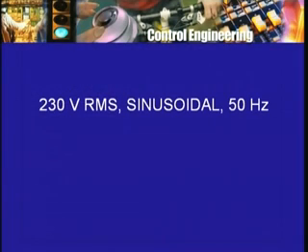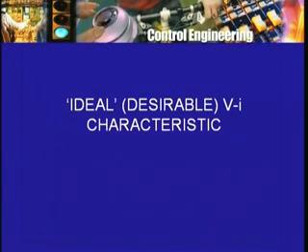In the case of the AC power supply, let's say 230 volts, it should remain in RMS value, the waveform should remain sinusoidal, and the frequency should remain at 50 hertz or 50 cycles per second. So in this sense, one talks about an ideal voltage source, but here the word ideal also means that the voltage of the source does not depend on the current.